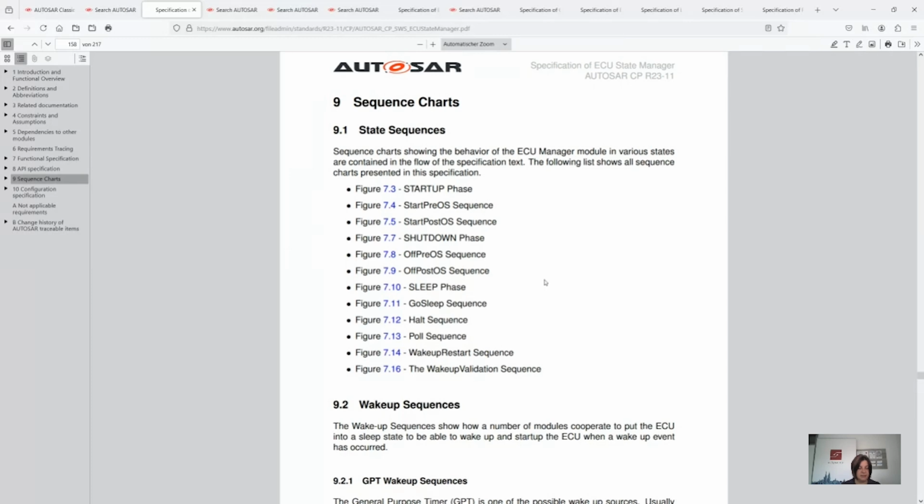So this sequence is not so easy, because all the ECUs within a vehicle have to wake up step by step, and also go to sleep step by step. You don't want to have malfunctions. You want to have the ECUs available which you need right now. So this sequence is not easy peasy. It's really something coordinated, and the wake up sequence is on all the ECUs,